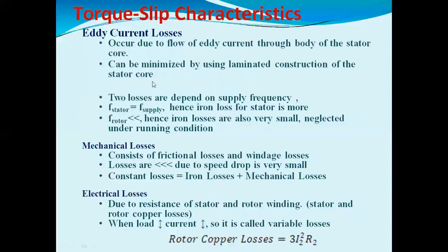And that is called the eddy current loss, which occurs due to the flow of eddy current through the body of the stator core. It can be minimized by using laminated construction of the stator core. So the two losses that we have already seen, the eddy current loss and the hysteresis loss, are dependent on supply frequency.